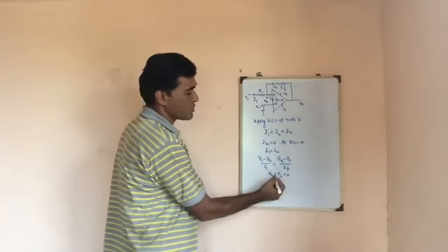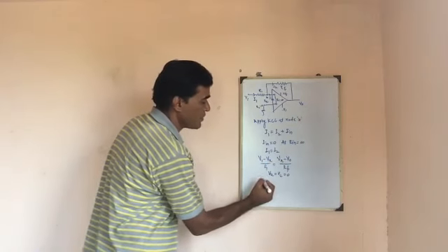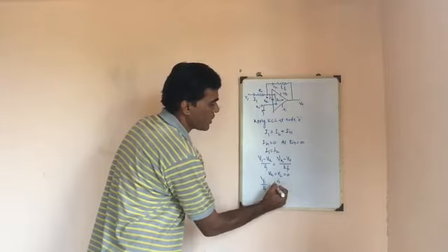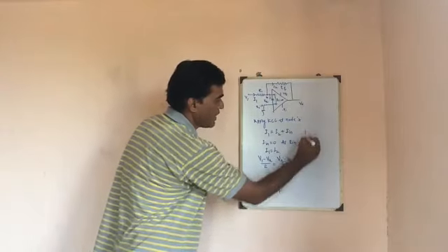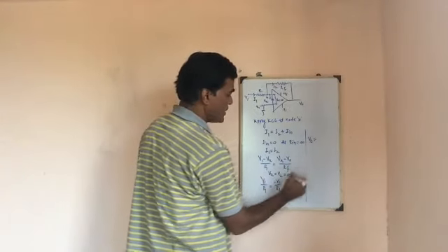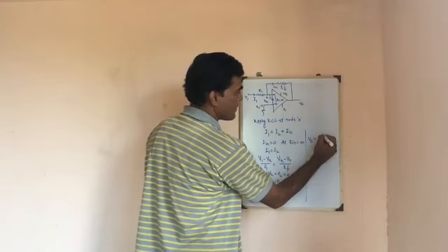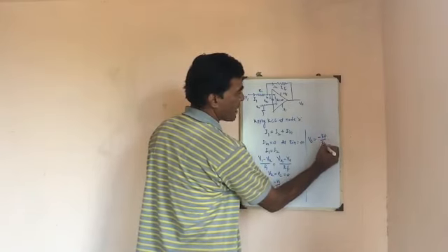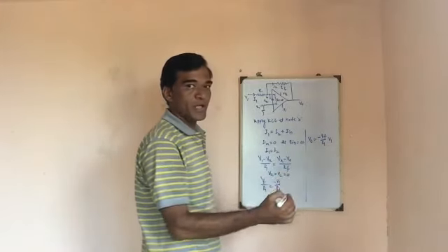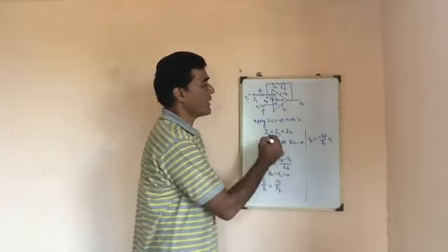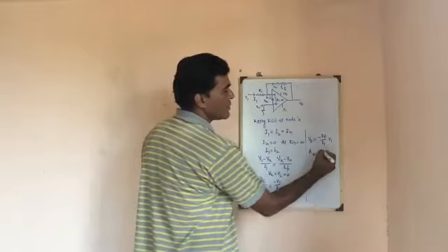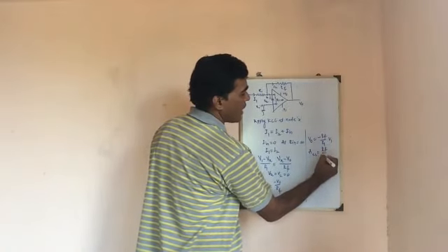and it is equal to 0. Substituting Vx equal to 0 in this expression, we get V1 divided by R1 equal to minus V0 divided by Rf. Hence I can write the output voltage V0 equal to minus Rf by R1 into V1, where Rf by R1 is known as the closed loop gain of an inverting amplifier. Here ACL, the closed loop gain, is equal to Rf by R1.